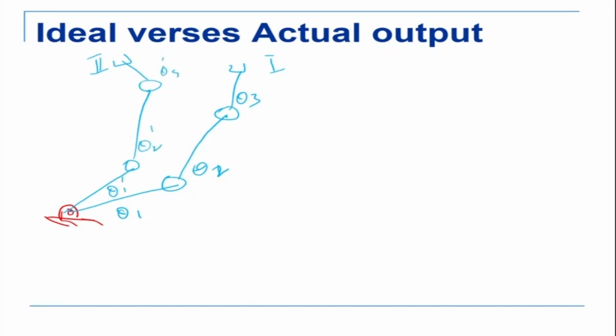Then for a respective joint, it will compute theta 1 dash minus theta 1 and generate an error, say del E. The controller then will design a PD, a PPD, or a PID controller, which we studied in the last few classes, to make this error go towards 0. But in the process, we'll see that there are a lot of errors inbuilt in the system, because of which the manipulator may not be able to make this error equal to 0 and may not exactly reach that position. So these are some of the terms used by the manufacturer to specify how good a robot is.